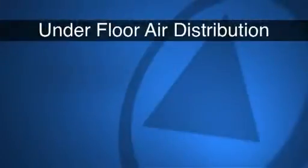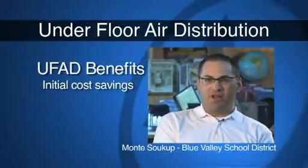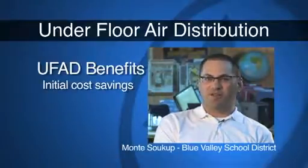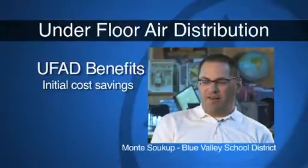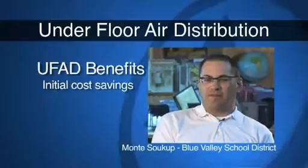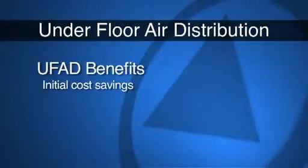Now let's explore the initial cost savings to be gained with underfloor from the equipment and installation perspectives. Probably one of the biggest savings is fan horsepower, because most of the energy in your system is lost in the delivery of the actual air. It's a fan motor. So with a displacement system and the underfloor air, we have a lower plenum pressure, so it takes less fan energy to deliver the air.